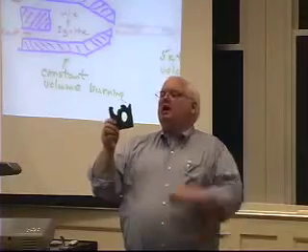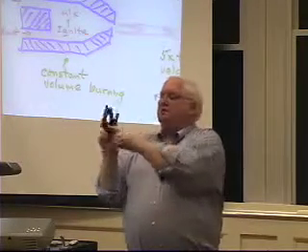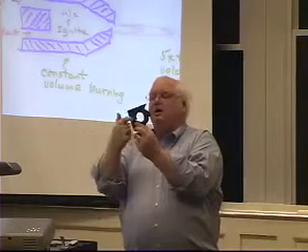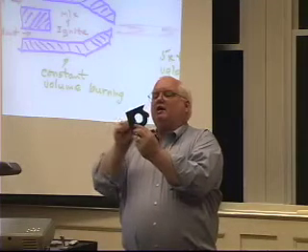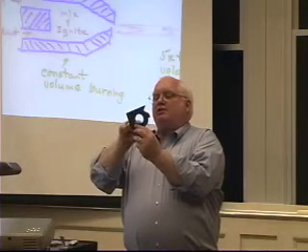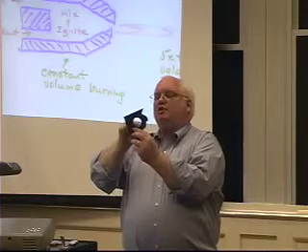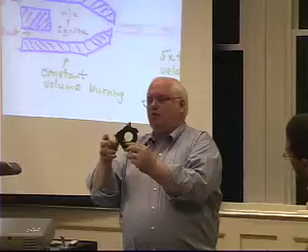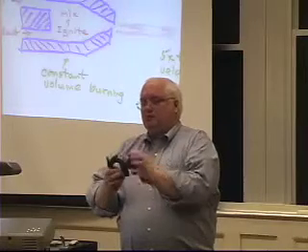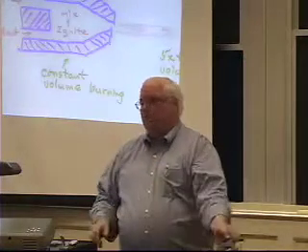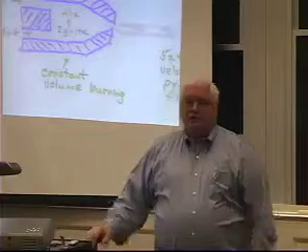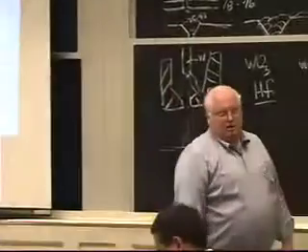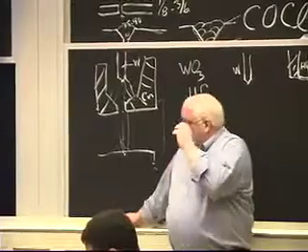This is a plasma cut piece of carbon steel. You can see where they drilled the first hole. They started out here, just like they did with that laser cut on the sheet metal. They started here where you're not interested in things. You cut out and then you make a perfect circle. A perfect circle, you can make a perfect cut because there are no corners. You look on some of the corners and you'll see the corners are not perfect. It depends on the radius of the corner. That's one of the problems. They tried to work ways around it. They did work a way around it.